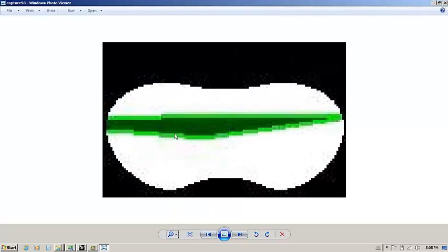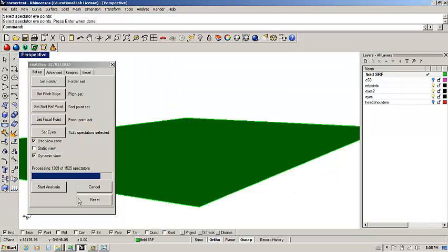You can take a closer look at one of those. And what's essentially happening is that we're going to count all the green pixels inside this cone of view, and that represents the area of the pitch that that particular spectator can see. You can see this masking zone has been applied over the top. So as we're doing that analysis, we're also calculating the C value and storing the XYZ coordinates. This is also set up to look at the possible obstructions, so you can set up spectators in front and essentially measure the area that's being obstructed by the backs of other spectators' heads.